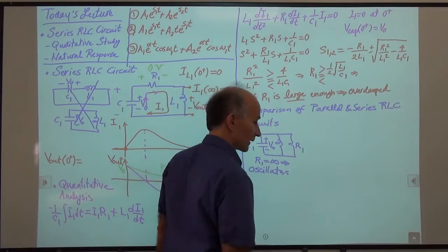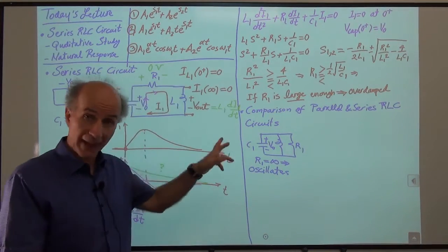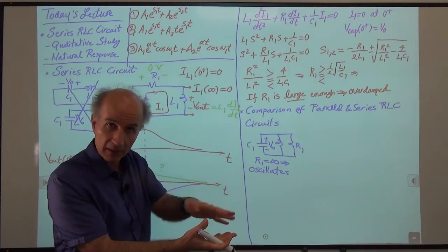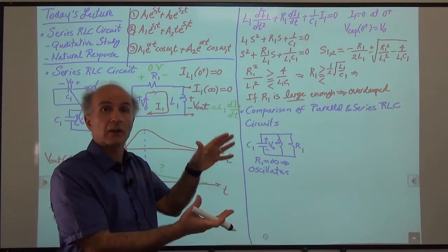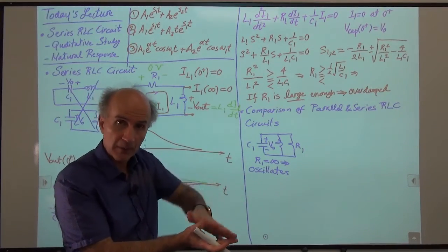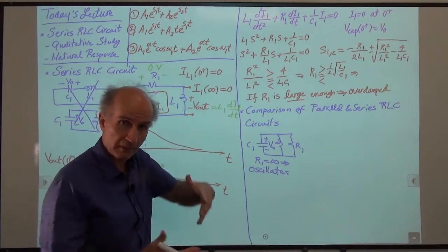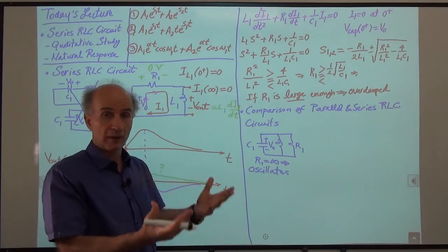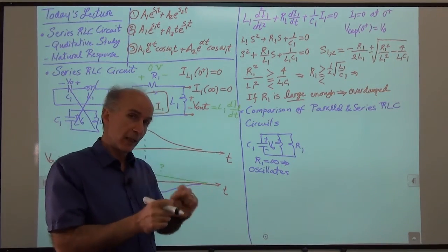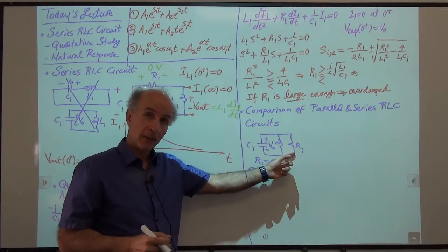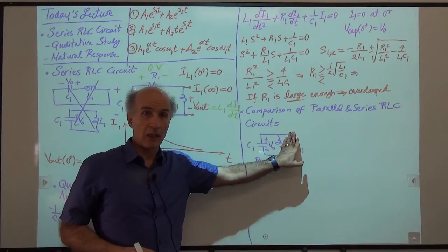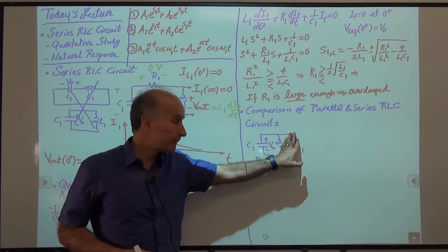The circuit oscillates, right? So we start from that point. We say, okay, now if R1 is not infinity, anything less than infinity, it will not oscillate forever, it will oscillate and decay. And if R1 becomes smaller and smaller, that decay becomes faster, and eventually we don't have any oscillation. All right, so the starting point is when R1 is infinity, so that the circuit reduces to something that we know and we intuitively understand.